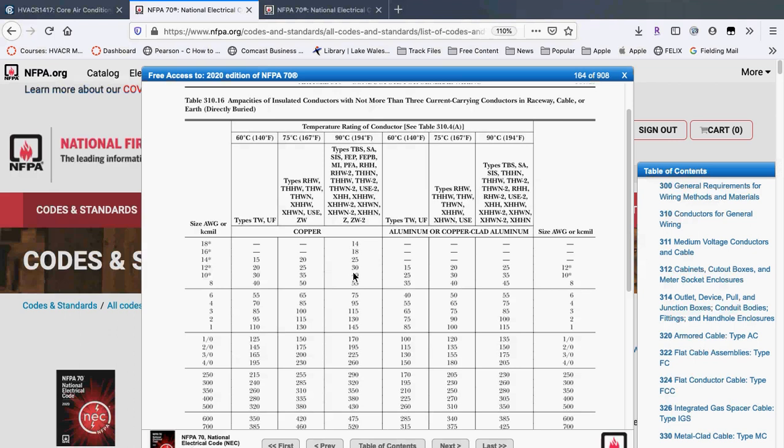Okay, so could I be sized properly at one voltage and not be sized properly at another voltage? Yes. Yeah, that's why voltage drop, and don't forget the power company can alter voltages. I'm going to tell you, my power in my house ranges between 240 volts roughly at night and jumps to 252 during the day. Okay, that's a pretty significant voltage swing.